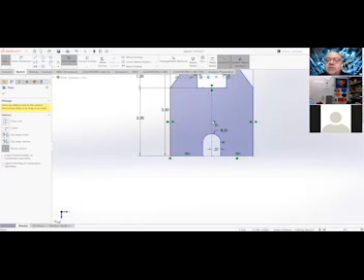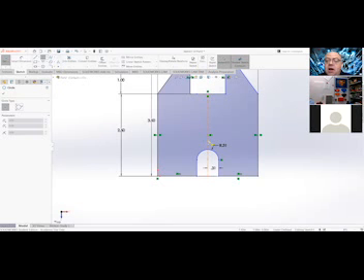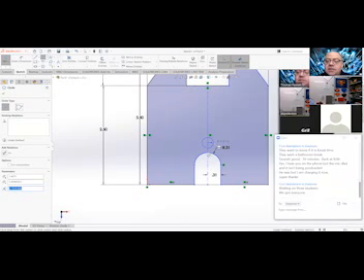Okay, one last circle to do. This is going to be, again, circle command, do the center radius circle, and this one's going to be right on that center line we drew. Now, when I float over it, notice that yellow square in the center. Do not put your circle there. If you put it there, we won't be able to move it into the right position. So you can put it above, you can put it below. It will just kind of point that pencil to the line and left click and drag out that circle.